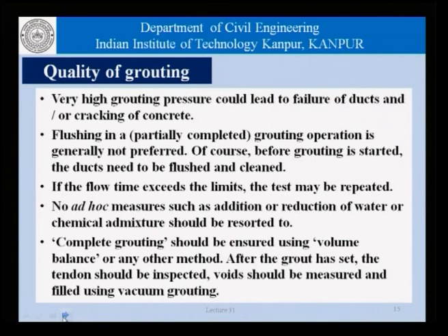So, basically there is very little that we can do once we are grouting a post-tensioned pre-stressed concrete tendon. We do not know if all the space in the duct which was supposed to be occupied by the grout has been occupied by the grout, other than by doing some kind of volume balance or carrying out non-destructive tests, which could be carried out while the grouting operation is being carried on or after the grout has set, and then we look for pockets of air.